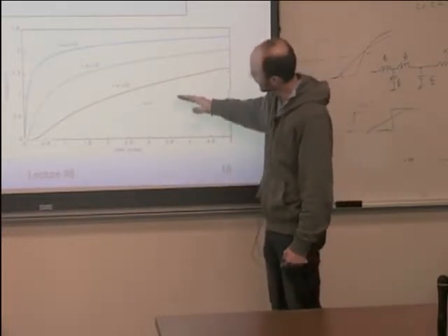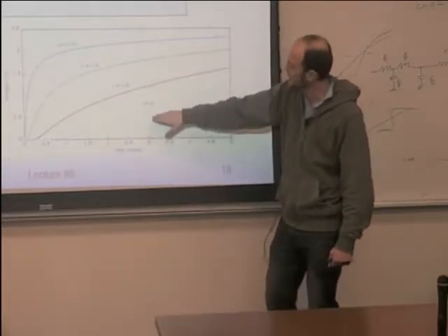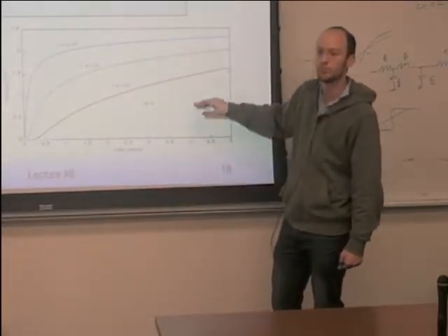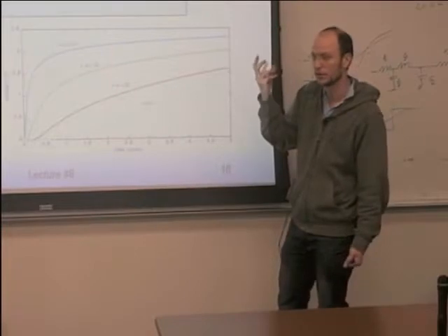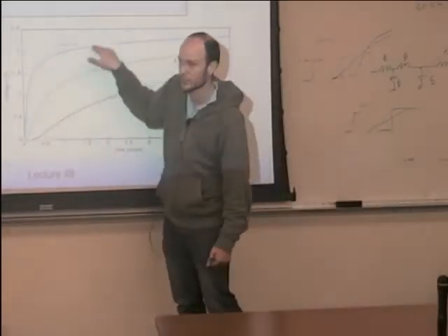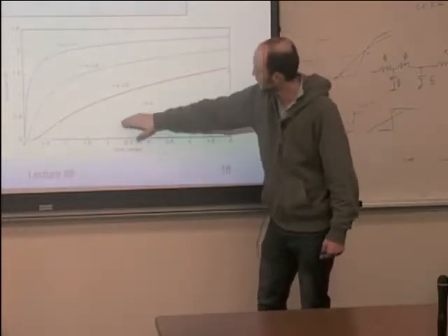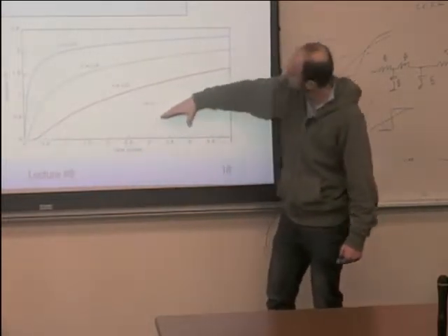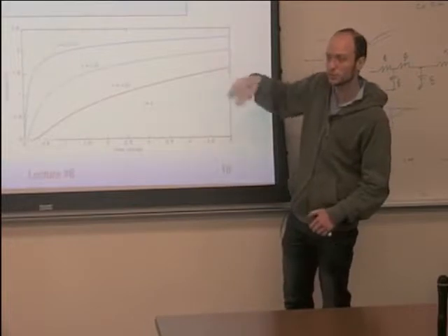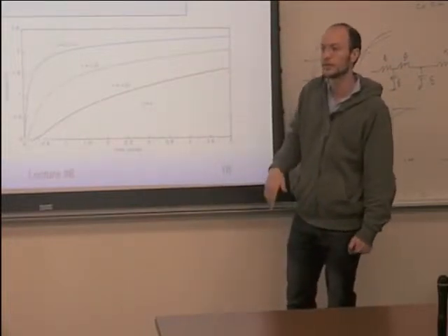And this rise time, you will never get a signal that looks like this at the output of a single RC network, okay? Because you will always get a signal that looks like this, but maybe translated in time. This is just a slow rise because of the distributed nature, okay?